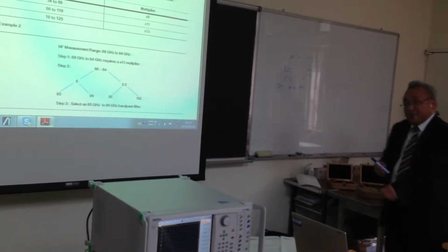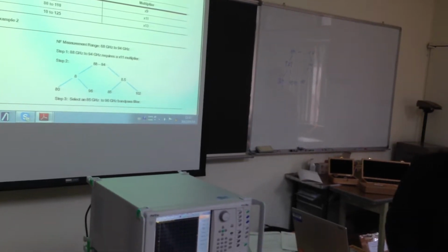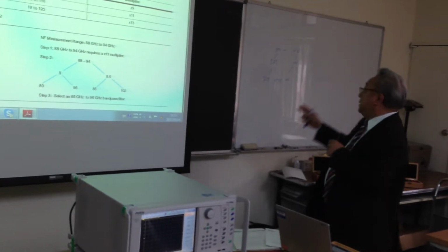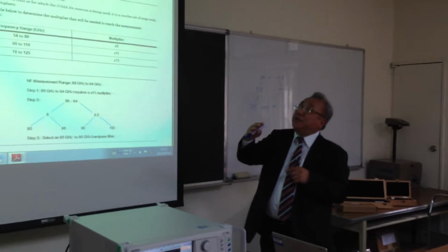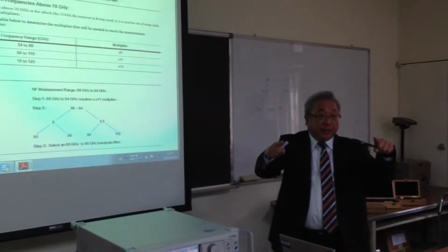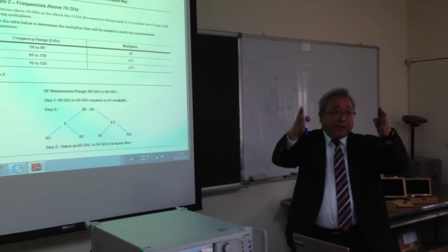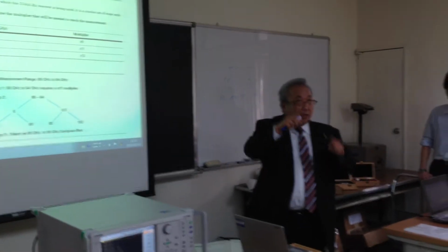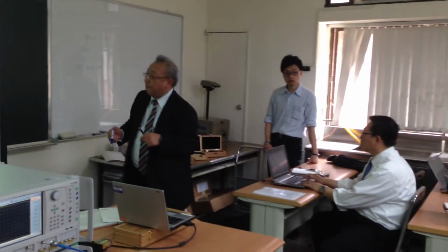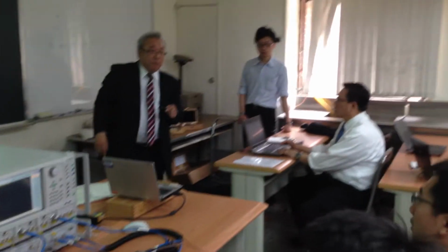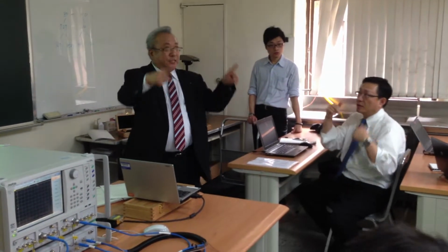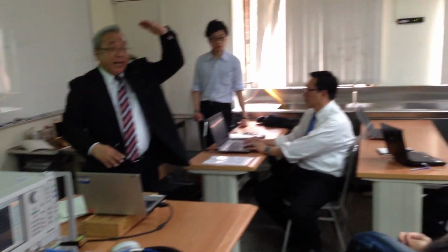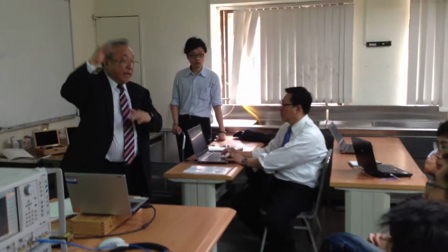How about the specification of the bandpass filter? Sometimes the rejection at this frequency is maybe about 15 dB. Sorry, the rejection in the stop band over 15 dB is maybe enough. So not so high rejection. No need for that high rejection.